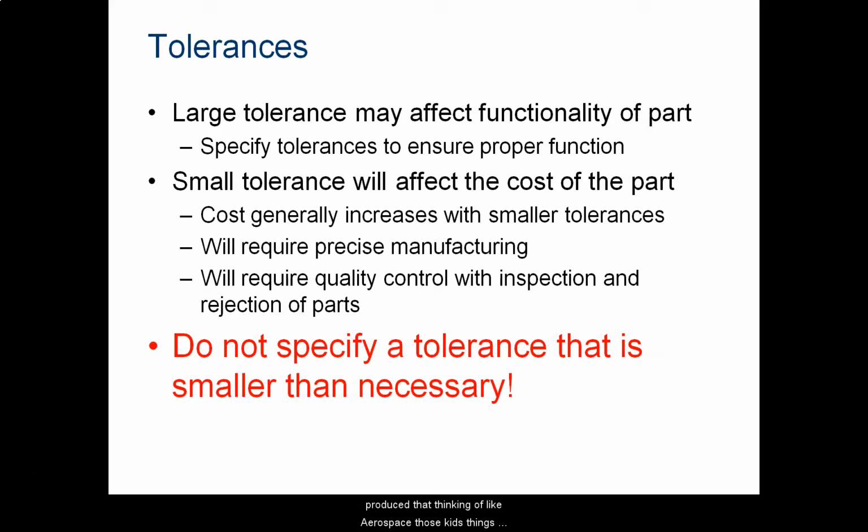to actually produce that go up. Think of aerospace, where even a thousandth of an inch makes a difference in vibration. If you're building airplane parts, they can't be off by more than a thousandth of an inch because it will create vibration, and then it'll eventually cause fatigue and parts to break. So the manufacturing cost for certain parts to have them that precise ends up being really extreme because of the quantity of parts the manufacturer ends up scrapping because they don't meet the tolerances or the design specifications.